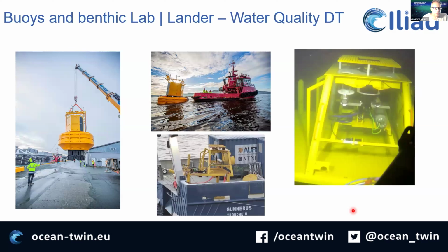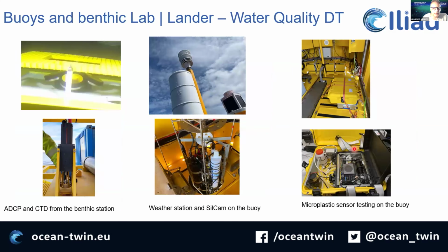And we also move to another system in Norway, in the North Sea, where they have deployed this very big buoy, as you can see, with a benthic observatory. This is a highly precise and accurate set of sensors where all the data are collected in a data logger. And as you can see, they have ADCPs for the measurement of currents and waves.